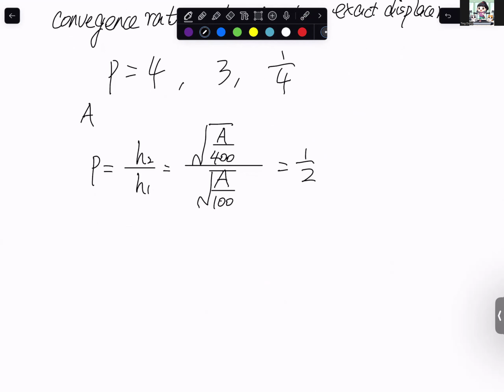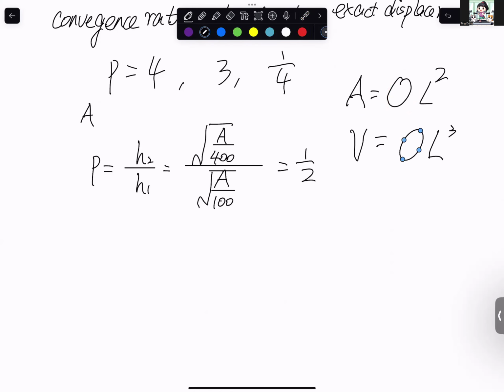It's the same. So for the triangle element, area is equal to a coefficient times the edge length squared, let's just use L squared, right? And then when you take the ratio, this coefficient is gone. No matter if it's a triangle element or another shape, it doesn't matter. Including if you use a tetrahedral element, assume the structure has the same volume, and the edge length, let's use L cubed, with a coefficient in front, and the coefficient cancels out in the calculation.